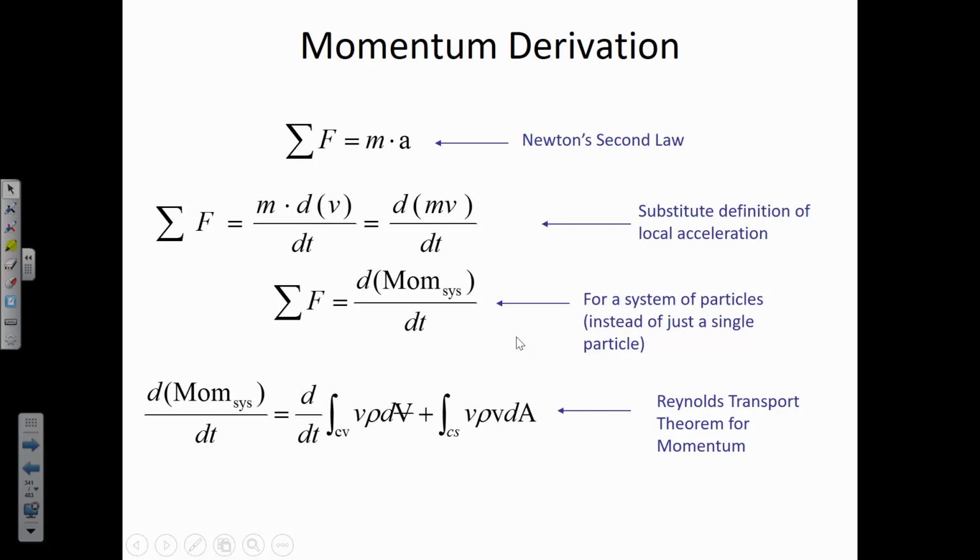Later on, when we talk about sign convention, we need to be careful to retain the directionality of the first velocity, but not the second one. If we had, for example, some fluid flowing to the left, which would be a negative sign for the direction of the velocity, and we put the negative sign into both of those v's, it would actually cancel out the directionality. So I just wanted to point out that these last terms are just the volumetric flow rate.